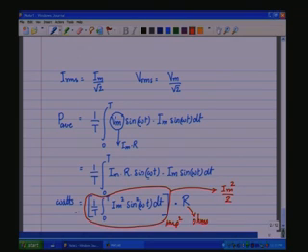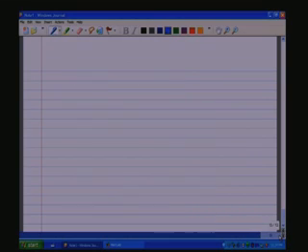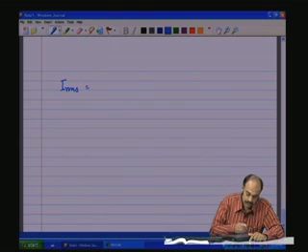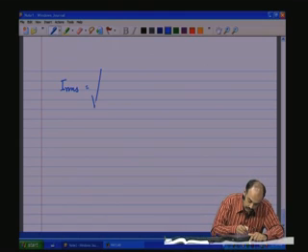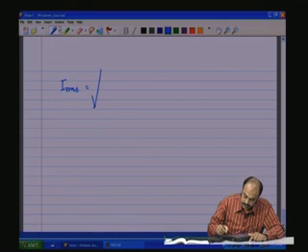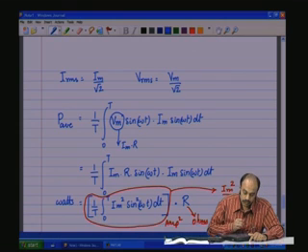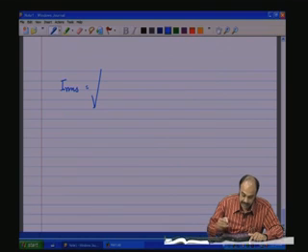So, RMS has to be equivalent to the root of this circled equation. So, if we write that down, I RMS is root of whatever was written in the circled portion, because that is equal to Im square by 2, that is amp square.